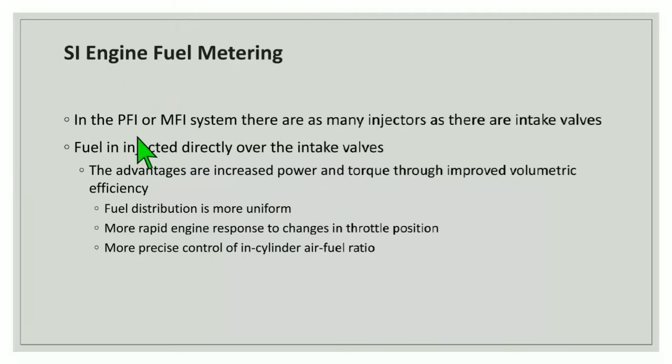In the PFI or MFI system, that means port fuel injection or multi-point fuel injection system, there are as many injectors as there are intake valves. Fuel is injected directly over the intake valves. The advantages are increased power and torque through improved volumetric efficiency, more uniform fuel distribution, more rapid engine response to changes in throttle position, and more precise control of in-cylinder air-fuel ratio.